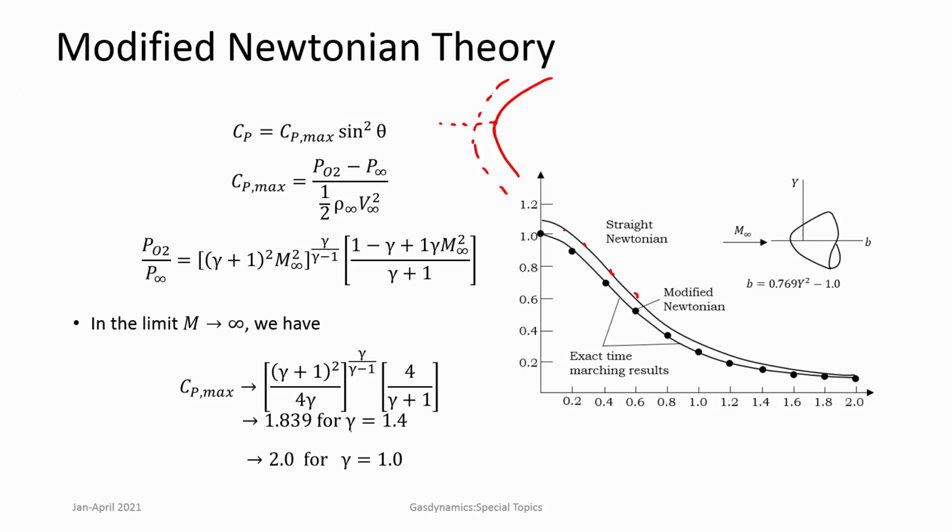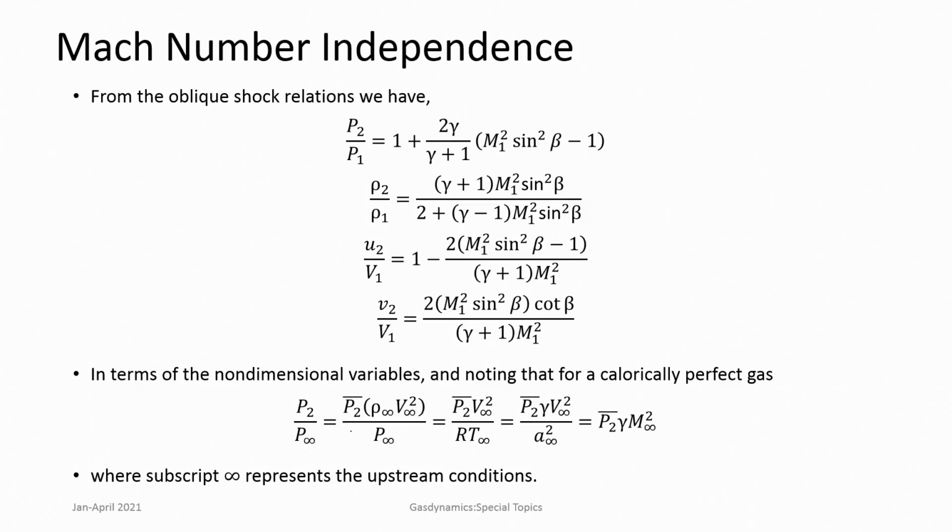So with these discussions, what one must understand is that while physical flow features in hypersonic flow become quite complex, the very fact of high Mach numbers allows certain simplicity, and surface inclination methods like Newtonian are quite useful in estimating the coefficient of pressure.